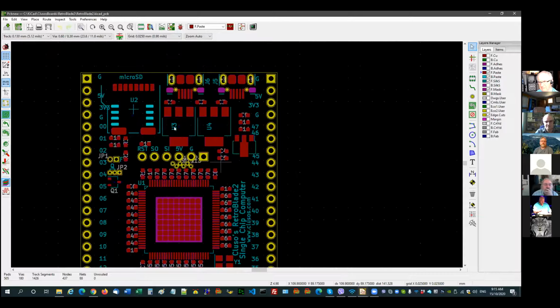They're my two big regulators and my smaller one. You'll notice I've got bypass caps on the input, directly on the output, then input there. They're not directly on the output there and over the other side. Again, when I'm running the 3.3, I've got an input capacitor here. I've got two output capacitors there, one bypass, one bulk.